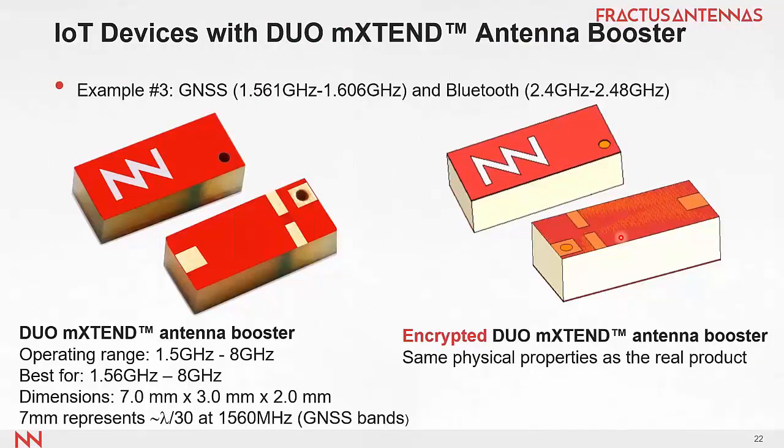Let's move now to another example. In this case, what we have is another component of the family of virtual antenna. It's called Duo because this is a dual port antenna, and we explain in our user manuals, and also in the user manual for CST, how you can fit this antenna in one port to operate at global navigation satellite systems, such as GPS, GLONASS, Beidou, in this frequency range, as well as in Bluetooth.